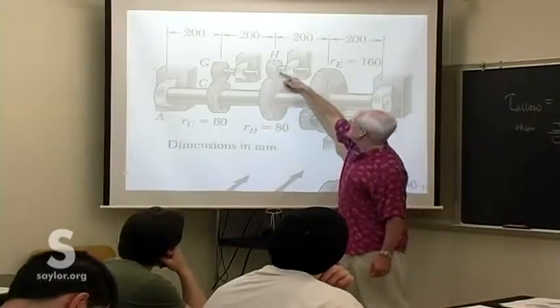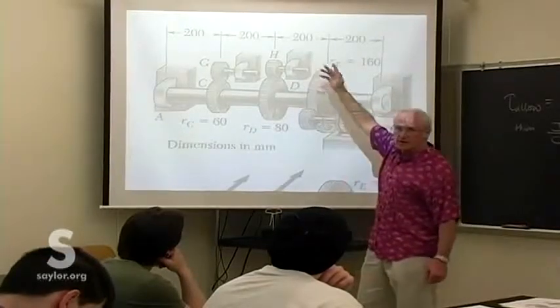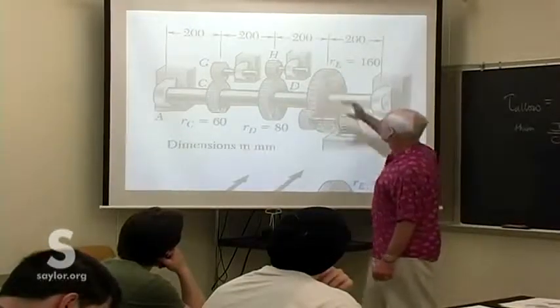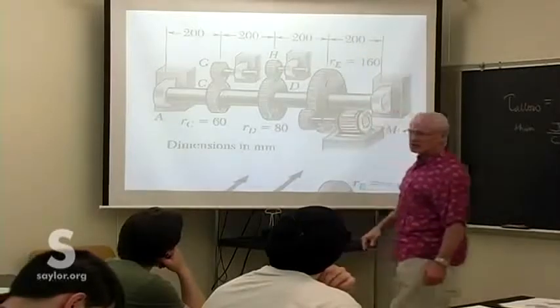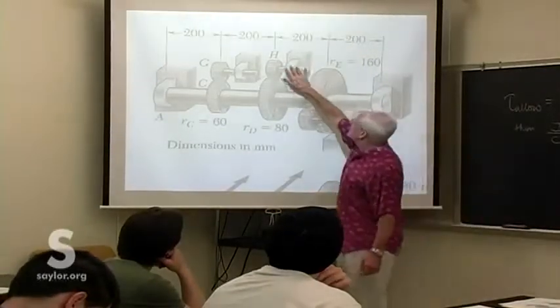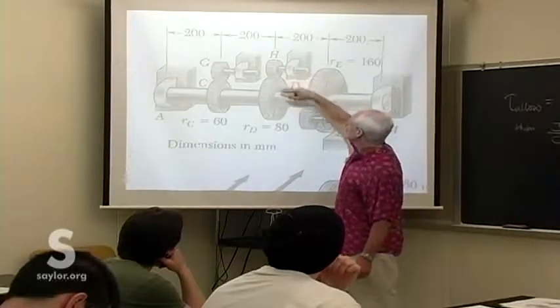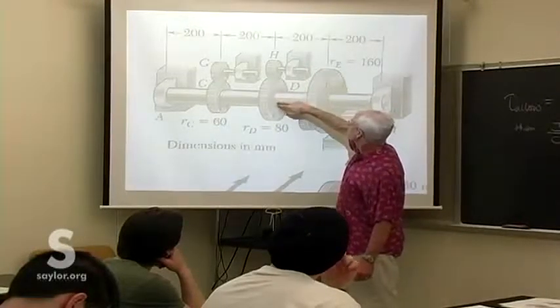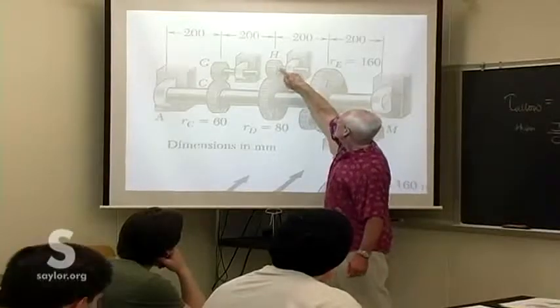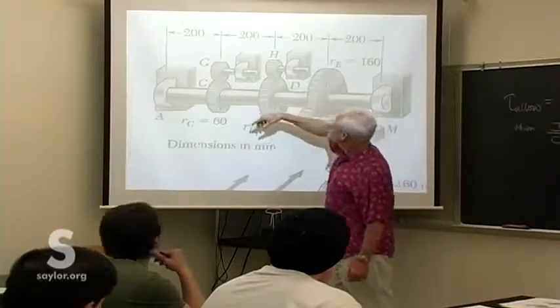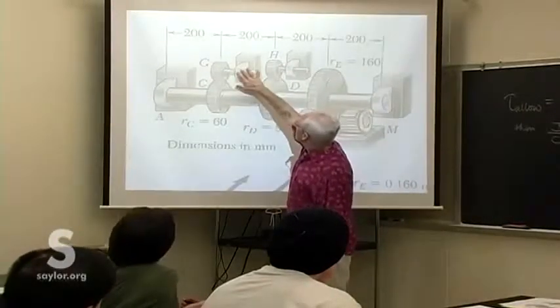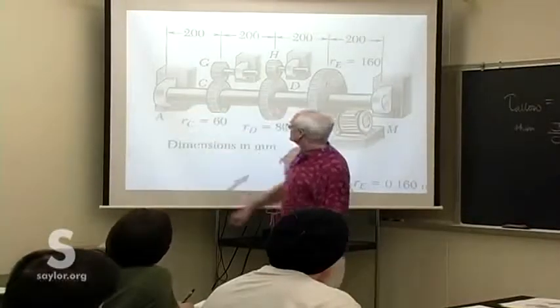This is gear D running some other generator or motor or some other thing, but we just simplify it with showing a gear. Don't take it that this business at H just spins freely and doesn't apply any of the forces that we're interested in. That's power takeoff. H is actually running something, but we're not going to show that entire thing. Same with G, and then another gear bearing at A.